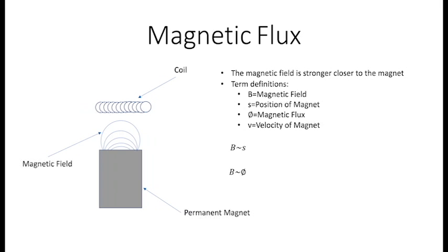the coil increases. The second conclusion comes from the definition of magnetic flux, that the flux is proportional to the strength of the magnetic field. From these two conclusions, we can then conclude that the position of the magnet with respect to the coil is proportional to the magnetic flux seen by the coil. We can even take this one step further by differentiating both sides, and then we can see that the velocity of the magnet's oscillations is proportional to the induced voltage in the coil.